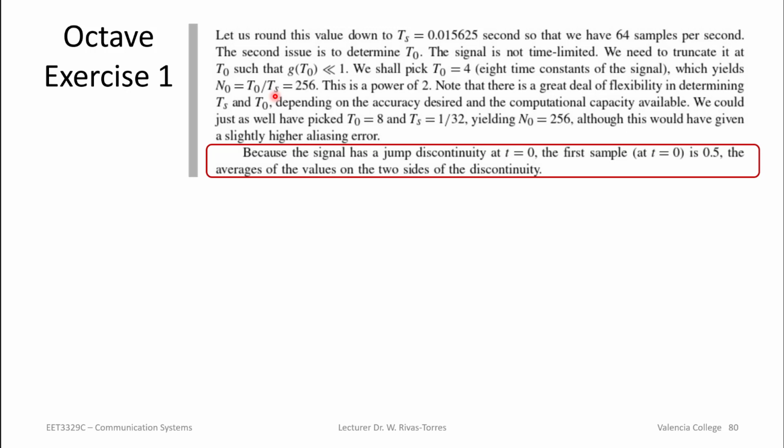In the real world, you never have that. Plus, that's a discontinuity. If you try to take the derivative of that, it goes to infinity. So it means that we don't know what to do with it at the end of the day. In the real world, that never happens. The signal actually always has what we call rise and fall times, and it takes the signal a certain time to get there, to go from 0 to 1. And by the way, that's also due to causality. You really can't go from no signal to all of a sudden having a signal at the output. That jump is not realistic or physically possible.